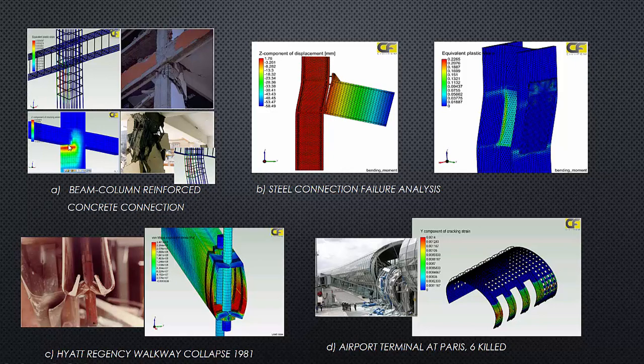Also, another great capability of CivilFEM is the contact between different elements. In this case, the beams were modeled using face-to-face contact with the adjacent column member here. Also, the cracking and crushing were introduced in the material properties. Also, the stress-strain material curve was used in this specific example.